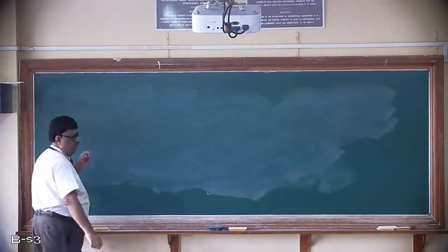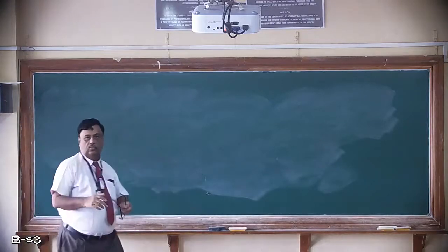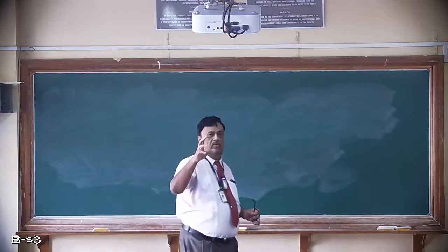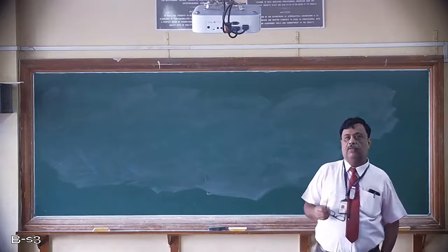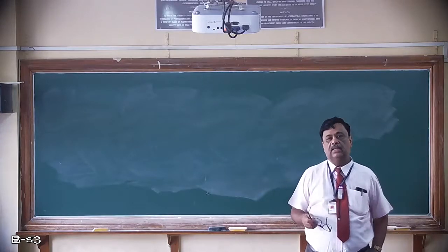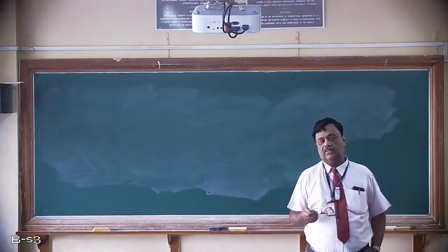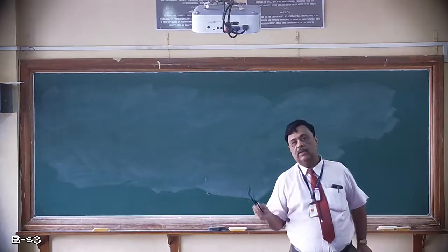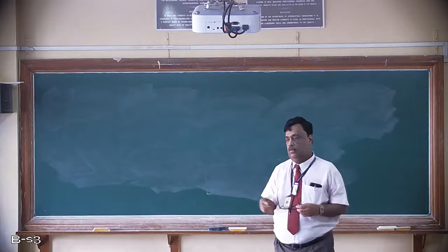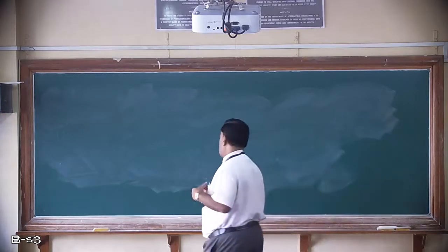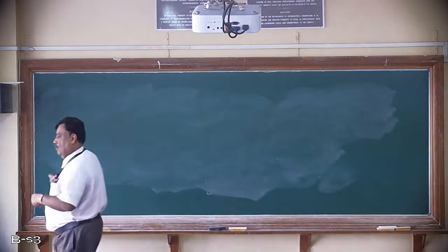Then you can make the global assembly of these two and solve for the nodal displacement with the given boundary conditions. KQ equal to F will be solved, and what we get is the nodal displacement. What has been asked is to find the nodal displacement at these points, especially Q1 and Q2. Okay, we will take up the remaining part in the next class.